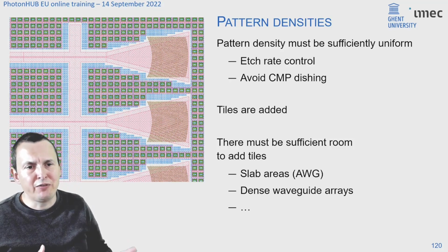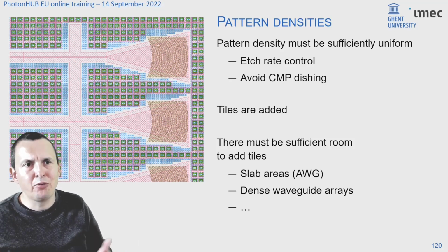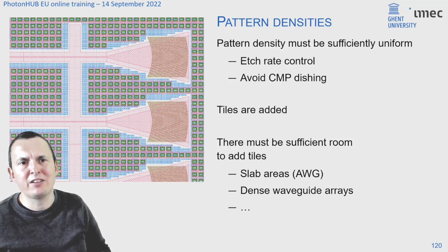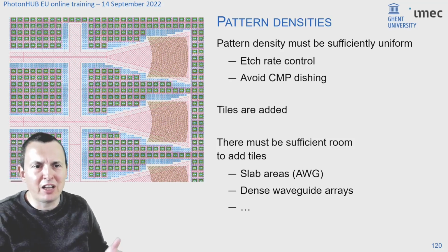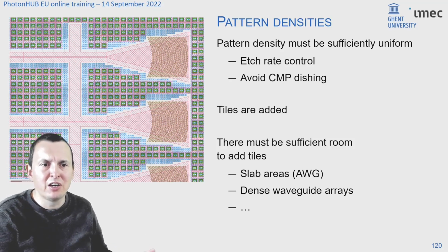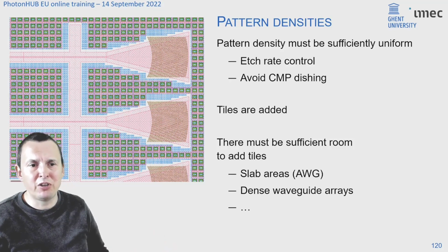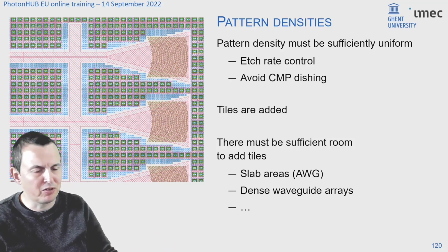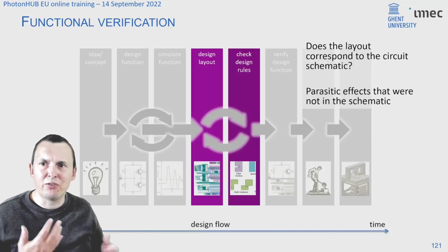And you have to be careful with designs that include such features, that you do not completely wreck the required pattern density of your fabrication process. And depending on the foundry, they might still allow you to go through with it at your own risk, but they might also just forbid your design from going into the fab, because the chances of success are going to be slim anyway.